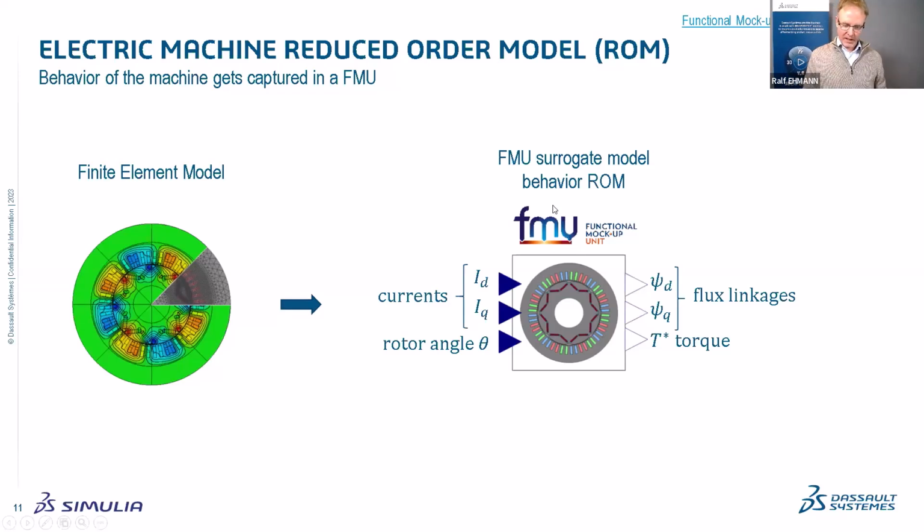And maybe additionally, the FMU is not just a lookup, it also contains the interpolation between the points. And this interpolation will take care that you have energy conservation, which is a quite important aspect, because you couple here with the electrical machine the electromagnetic domain with the mechanical domain. And obviously what you put in as electric power, you want to have out as mechanical power, and if you have some loss in between, this is not as it should be. So all of it is contained in this one exchange format.